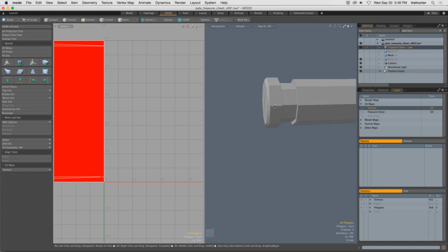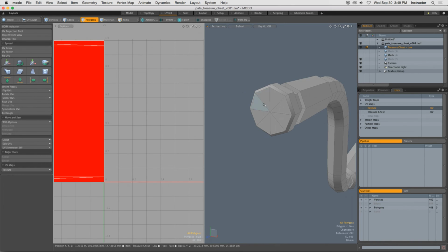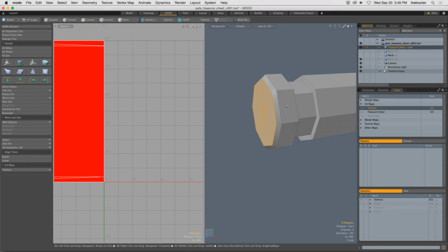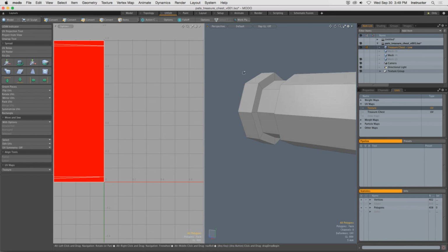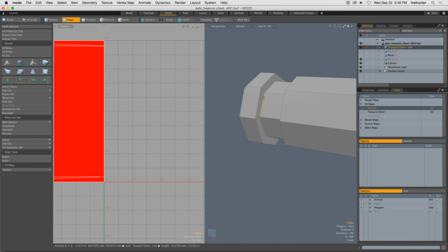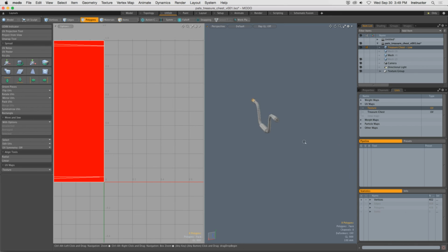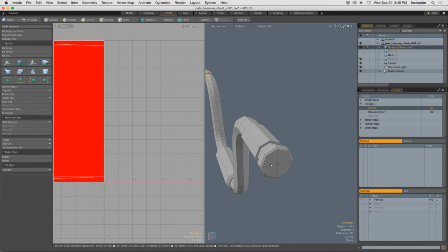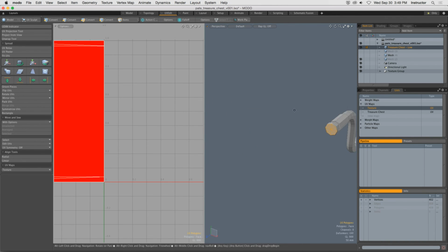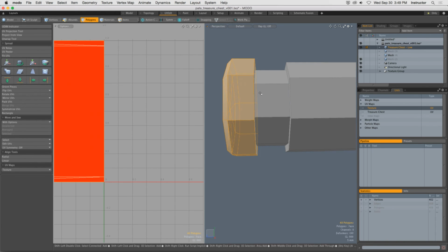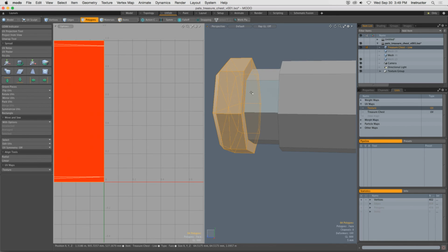Now we have to go in and figure out, now we can't have these caps down here. This is a problem for us with the unwrap tool. That's not going to work, okay? So what we're going to do is, there's two things that you can do. This is totally cool. You can go in, grab these polygons, do shift up arrow a couple times to expand the selection, like that, and then just hide the polygons. That's fine.